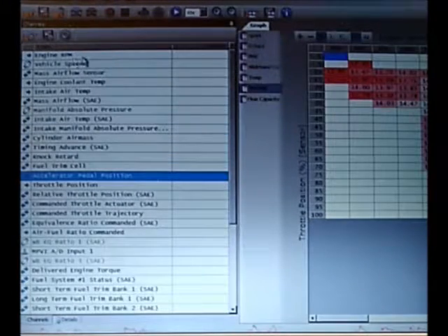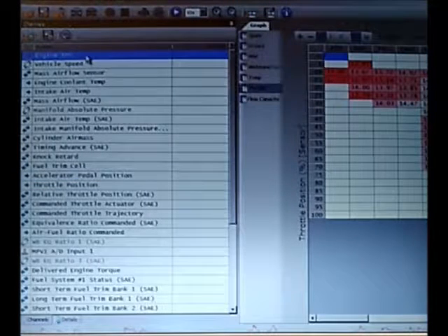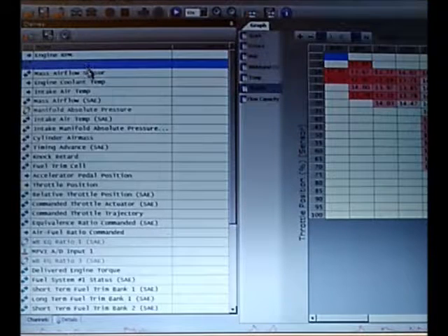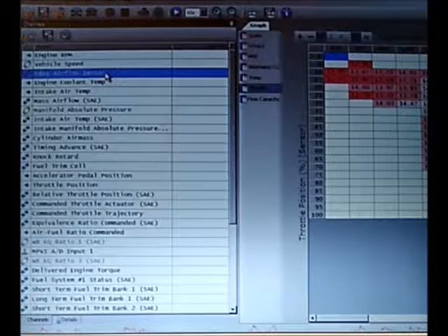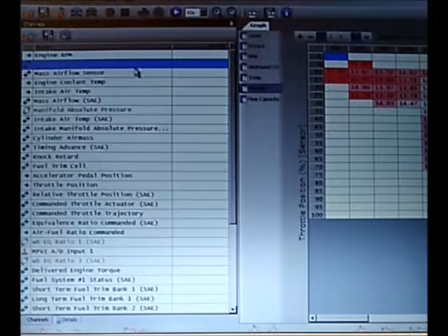I'm scanning engine RPM and vehicle speed. Engine RPM is very important because it's used in everything. You must scan that. Vehicle speed, I would recommend scanning it. For some reason, it's broken on my scan. I don't know why it doesn't work, but it doesn't. It's not totally necessary. It's just useful information to know from looking at your scan whether you were on the highway or not, but you don't need it.